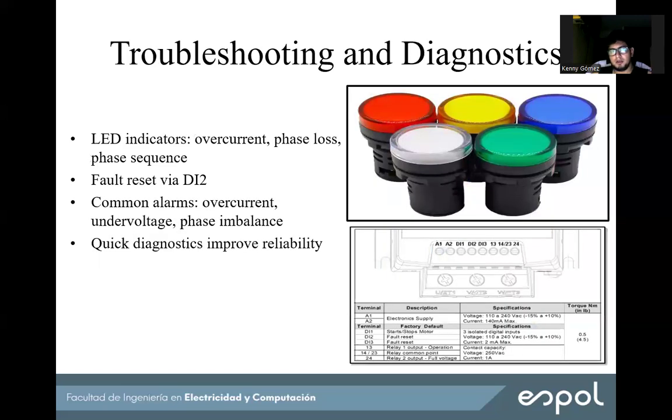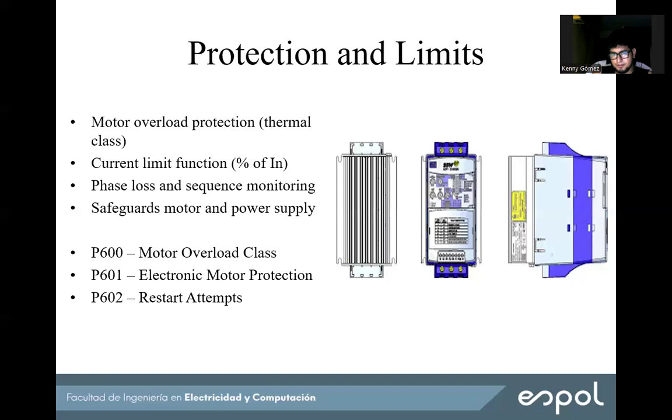The troubleshooting and diagnostics will be managed by LED indicators. It is about overcurrent, phase loss, or phase sequencing. At the same time, there will be a fault reset via DI2, with common alerts about overcurrent, undervoltage, and phase imbalance. Finally, quick diagnostics improve reliability.